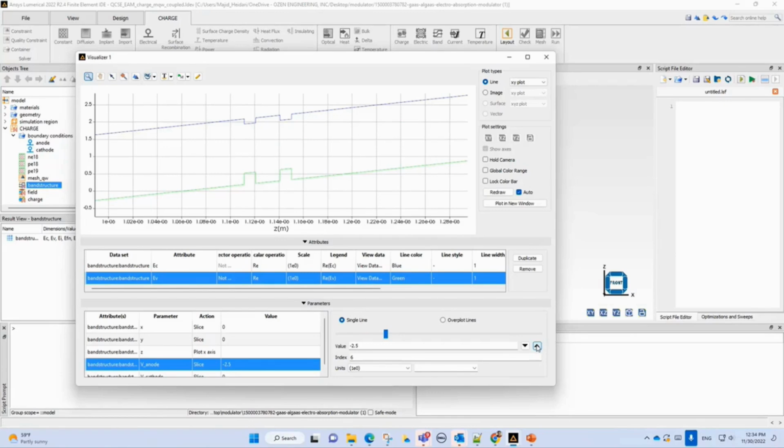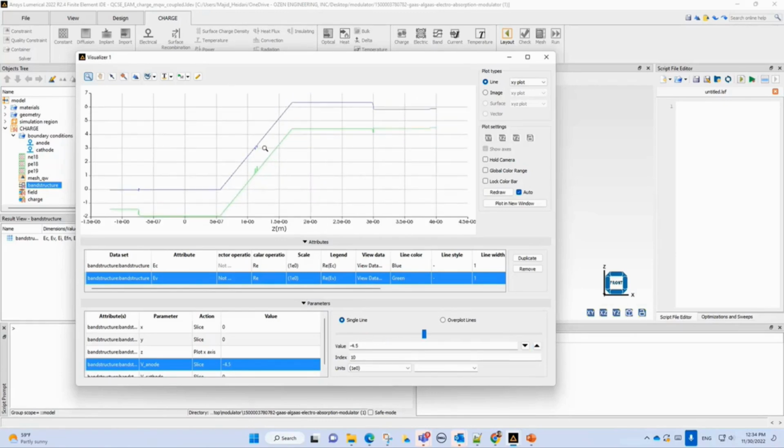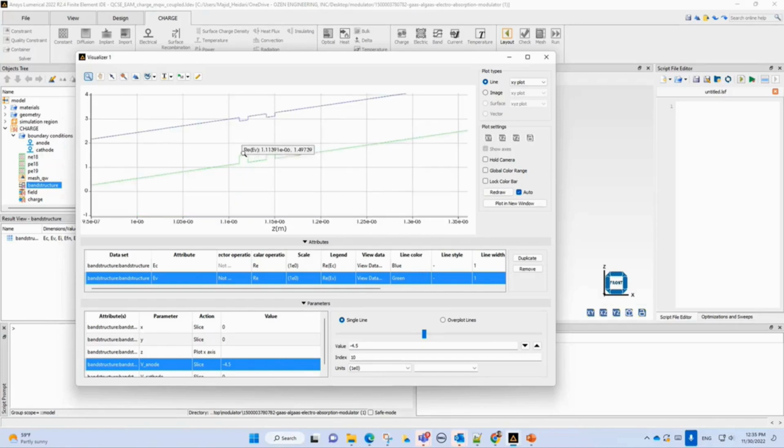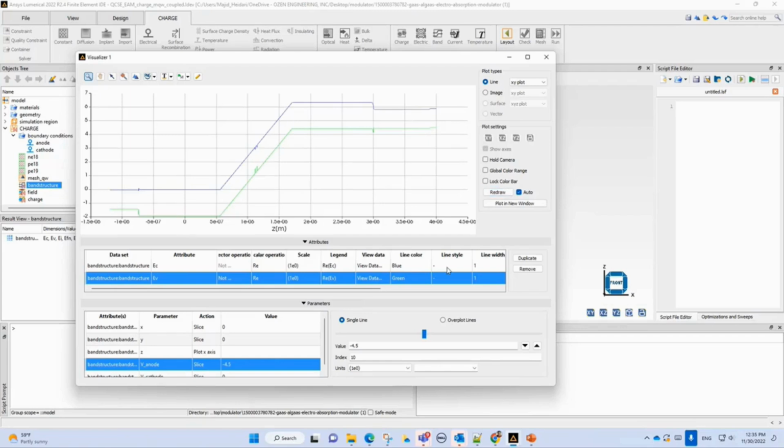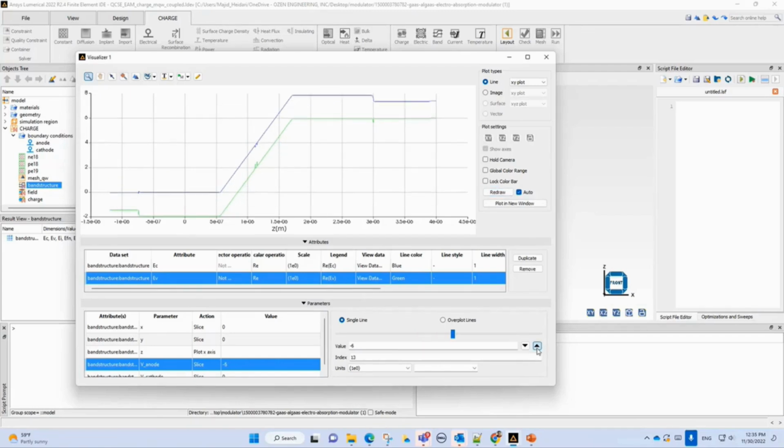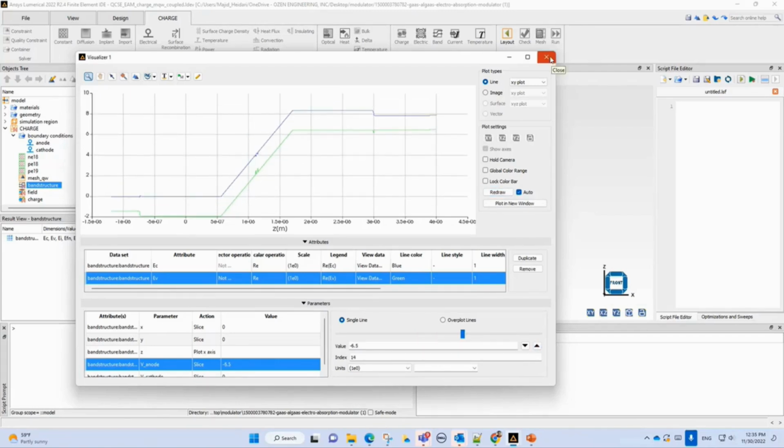You see the quantum well, and we remember that here is our P side of the PIN, and here is our N side. So here is GaAs, here is indium gallium arsenide, and indium gallium arsenide, and gallium arsenide, and also our quantum well here is gallium arsenide, and here is indium gallium arsenide. So it's quite handy, and you can see what's going on in the band structure.